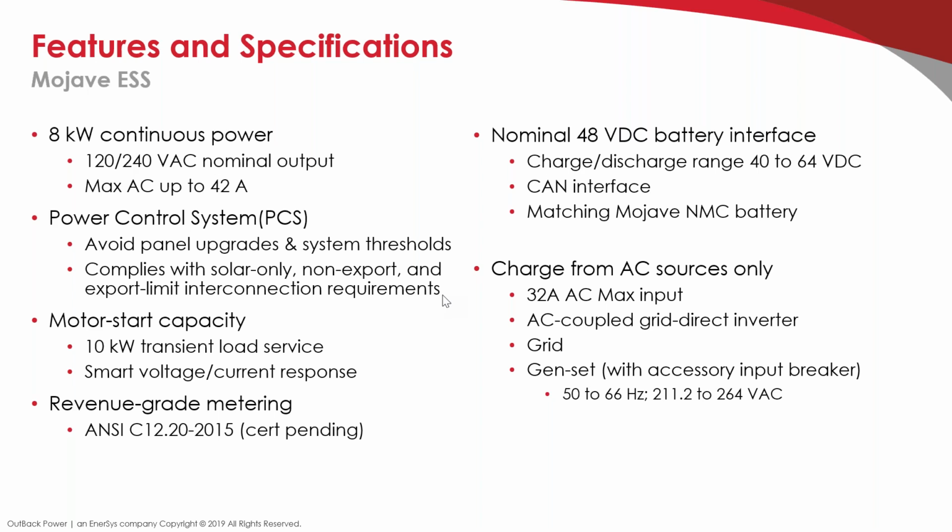And so what we've done, without just jacking all kinds of power into that, which gives us problems with the aforementioned power control system requirements, is we control the power to 10 kilowatts or below, and we let the voltage fall and hit it with enough current to get that motor started, or kick over whatever that inductive load is that's going to suck up all the current.